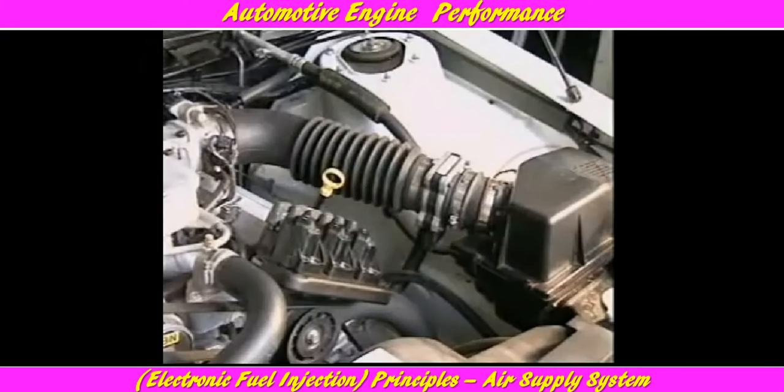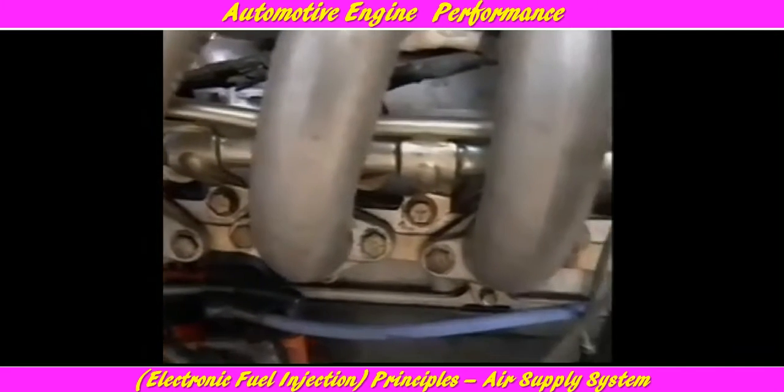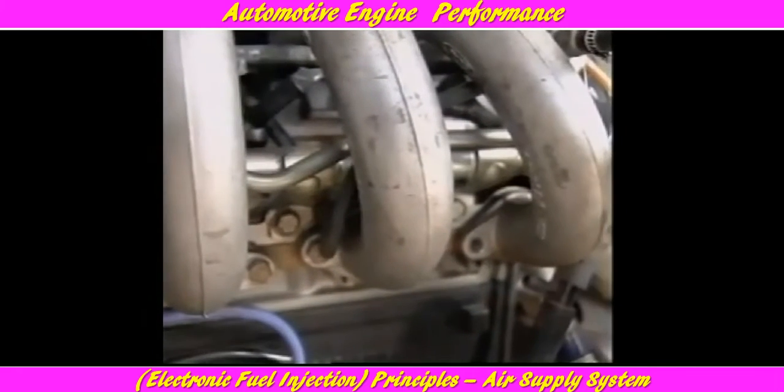This is why on most intake systems the air entry to the intake is away from engine heat, to ensure the entry of cool air. Since the manifold carries air only, it doesn't need to be heated by coolant. Filtered air arrives at the intake port as cold and dense as possible, ready for mixing with the fuel from the injector.